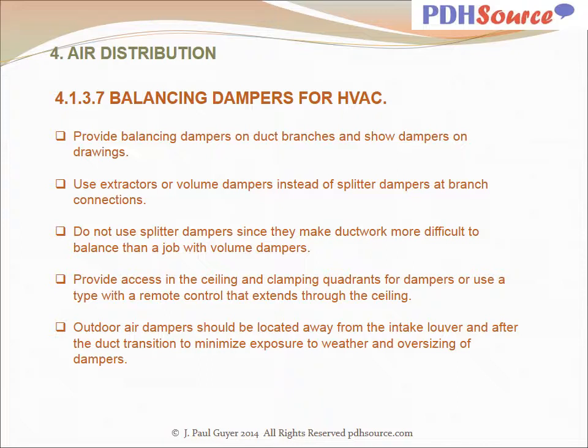Provide balancing dampers on duct branches and show dampers on drawings. Use extractors or volume dampers instead of splitter dampers at branch connections. Do not use splitter dampers since they make ductwork more difficult to balance than a job with volume dampers. Provide access in the ceiling and clamping quadrants for dampers or use a type with a remote control that extends through the ceiling. Outdoor air dampers should be located away from the intake louver and after the duct transition to minimize exposure to weather and oversizing of dampers.